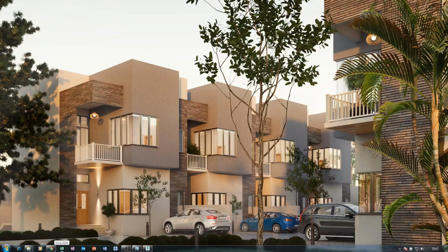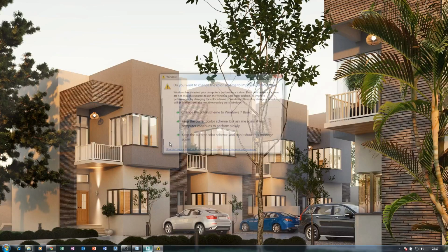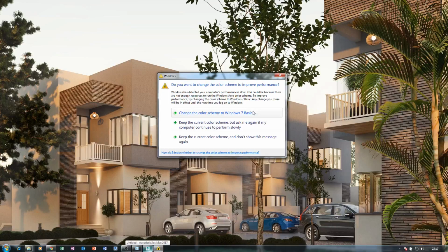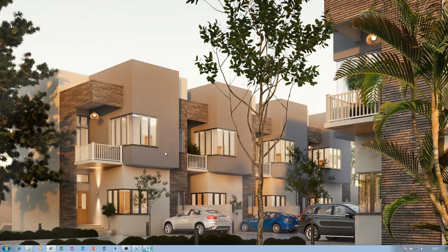it actually brings me to a very important thing that I think many people always make a mistake of. Having this building and this building here, and I'm still talking about framing now, does not mean that if I want to render, I should render the whole building, except if this building is different from this. And even if it is, that still doesn't mean I just carry my camera and create a wide angle that will just distort everything. No, I just have to find a perfect balance.